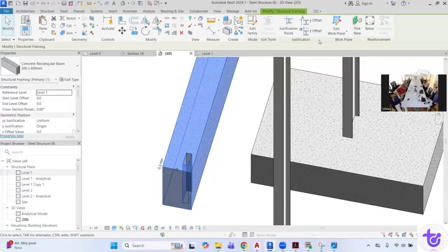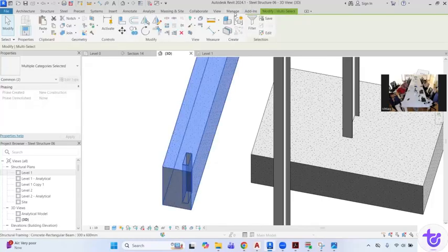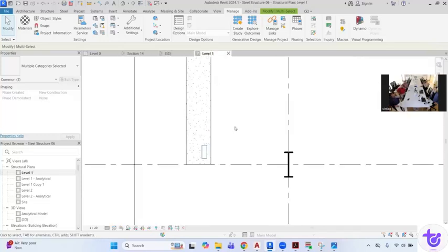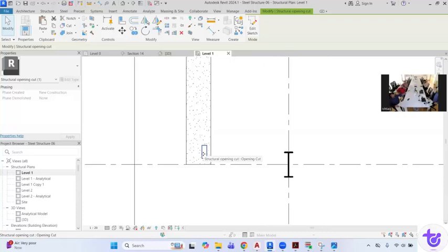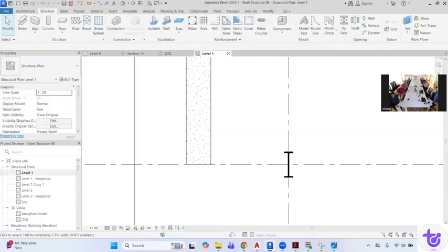And if you want to see in the warnings, manage, even if I'm selecting this, there is no warning. Because what is the reason now? We are cutting diagonally, which means the analytical line which is cutting through will be crossing the analytical line. It should get a warning. Exactly.